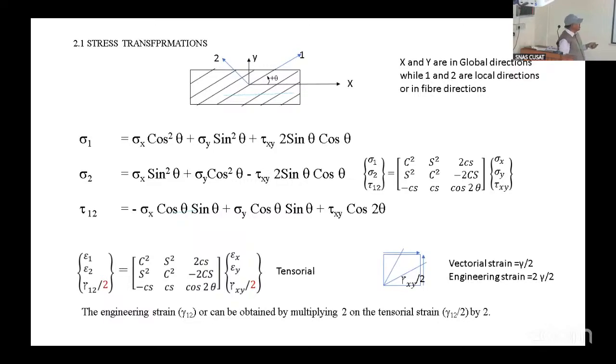So this is the thing. All these things you can get from test data. Sigma X, what is it? Now we will have it from material properties. If you do a complicated structure and you test it, put a strain gauge and measure epsilon X in the load direction. From there you transform and get it using the transformation.